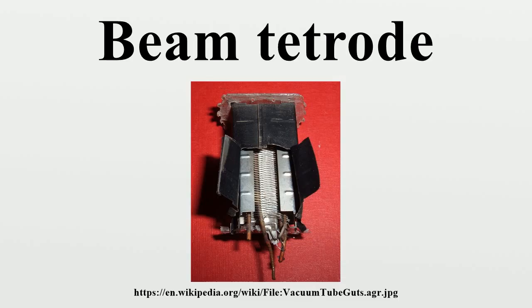The EMI design had the following advantages over the pentode. The screen grid current was about 5 to 10% of the anode current compared with about 20% for the pentode. Thus the beam tetrode was more power efficient. The design introduced significantly less third harmonic distortion into the signal than did the pentode. The design produced more output power than a similar pentode.